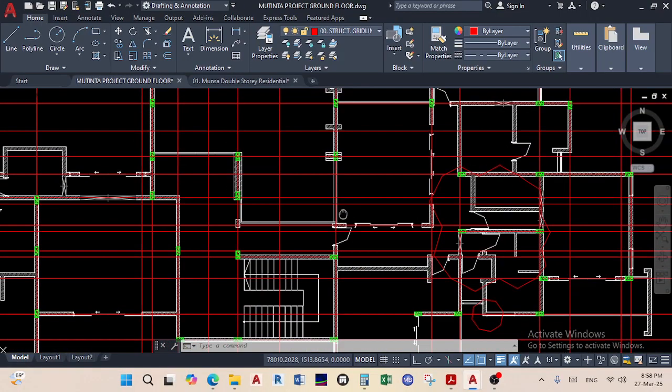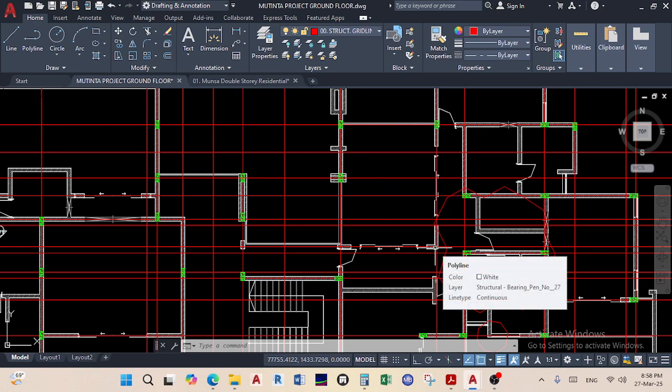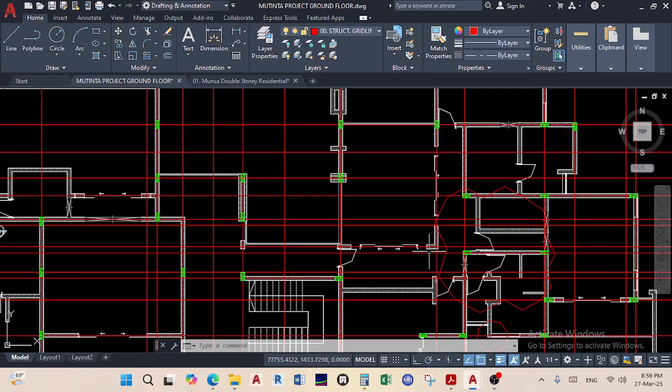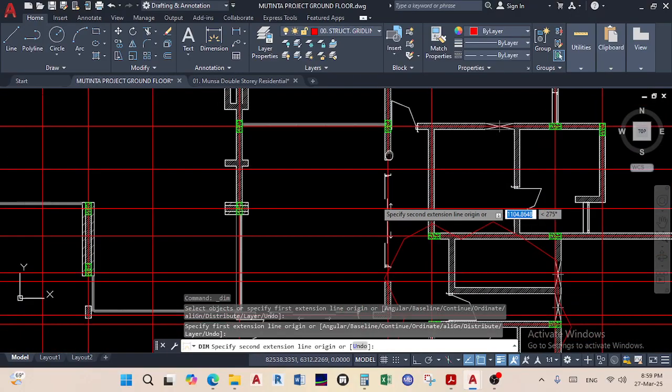But then we have from there to there, it would be nice to have a column, because where is this one going to rest with this direction? Here. So put one here, then where is this going to rest? If I move this one here, I have another there and there. I don't know what this distance is. So column placement is extremely important, guys.